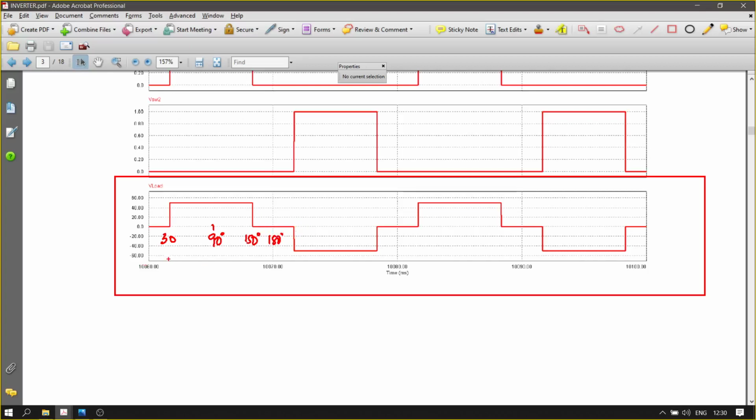That tells you that this is a quarter. Again, if you look at the symmetry, we also call this odd and quarter wave, isn't it? It is odd and quarter wave. Therefore you can find A1 is 0, because it's odd and quarter wave.